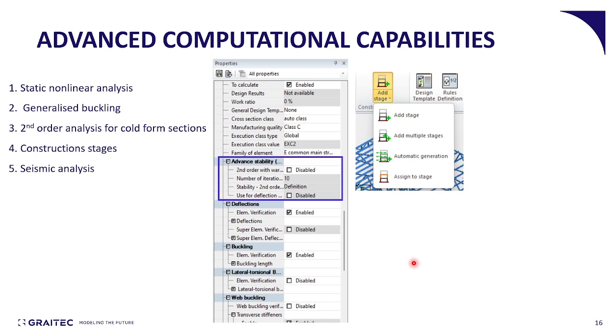In addition to that, Advanced Design also holds the options to perform modal analysis, pushover analysis for progressive collapse, and last but not least, time history analysis, dynamic analysis basically, where the user can add accelerograms or even make their own customized accelerogram and get results of the time history of the displacement of specific nodes.